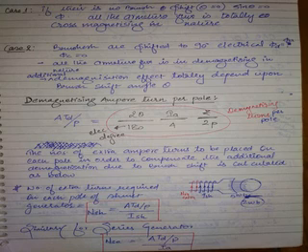Now the problem is, due to the effect of brush shift, if the brushes are shifted, what is happening in the armature? There is demagnetization, additional demagnetization. So let us consider that additional demagnetization is 2 Webers. So what will be the net flux in the machine? 3 Webers, right? These 2 Webers will oppose the 5 Webers, and automatically the net flux is 3.